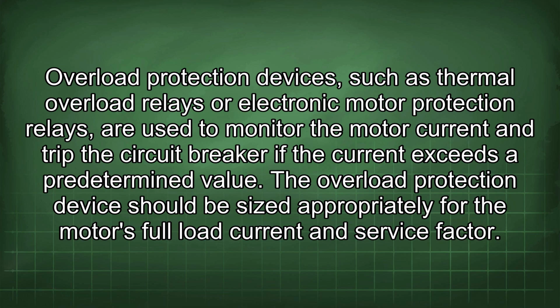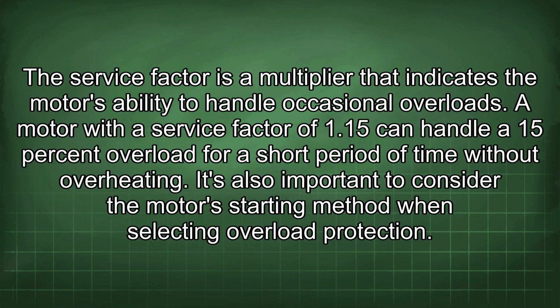The overload protection device should be sized appropriately for the motor's full load current and service factor. The service factor is a multiplier that indicates the motor's ability to handle occasional overloads. A motor with a service factor of 1.15 can handle a 15% overload for a short period of time without overheating.